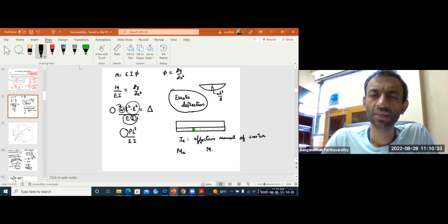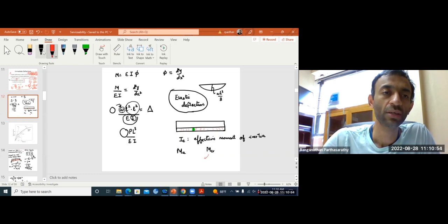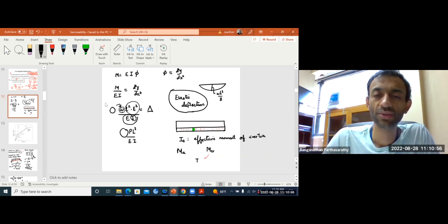Now MCR is your cracking moment, that means where it just cracks. Okay, MA is your applied moment, MCR is your cracking moment. So you can see that if you have not cracked, then you can use I uncracked transformed.